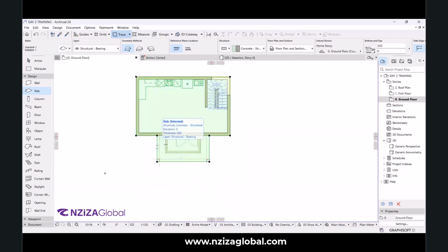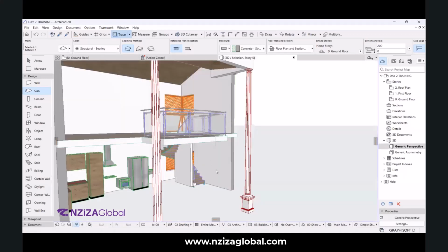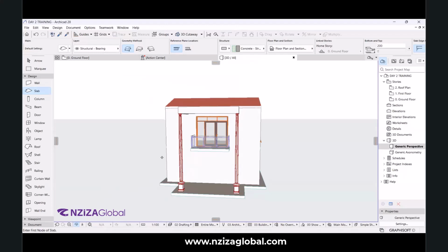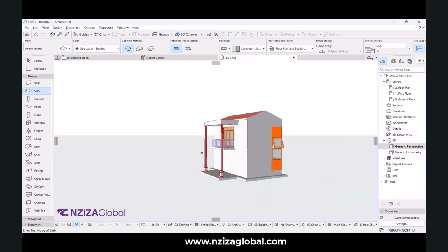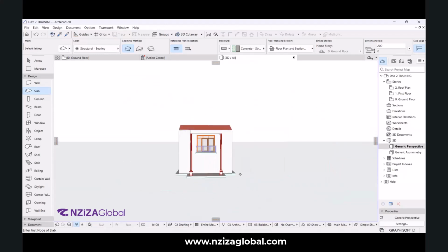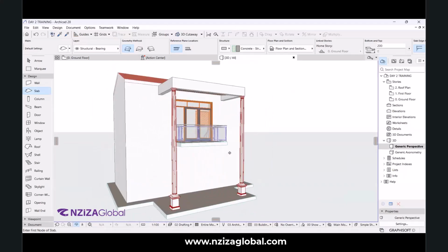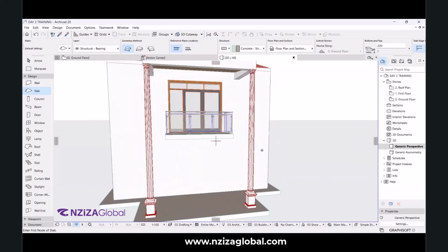Once that is done, we will select it and offset. Offset, we will select offset all edges and we'll put 500. Go into 3D and put F5. All our plan will be here. Now, let's go. The last thing of today.